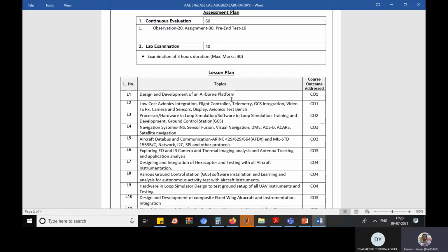So normally once you have a mold, we make the skins. You need a vacuum bagging process, and once you have composite skins with that particular shape, you integrate them first, making the shape. If you have two parts, then how are those parts going to be combined? Using some epoxy resin or hardener type of material. That requires some paste, and then you have to fix it.